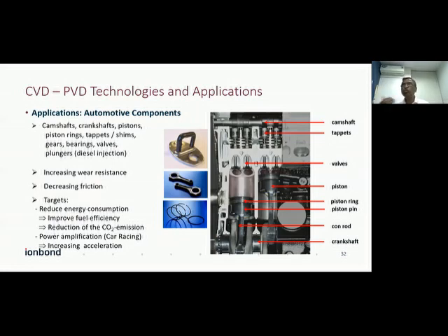So to reduce this friction, we have to have a frictionless coating, but zero friction is not possible. So we have to have the minimum friction. Now, we have seen just now in the concept coating, the coefficient of friction is 0.12. Still it is higher. If we go to the DLC coatings, that is amorphous diamond-like coating, then the friction is less than 0.1.